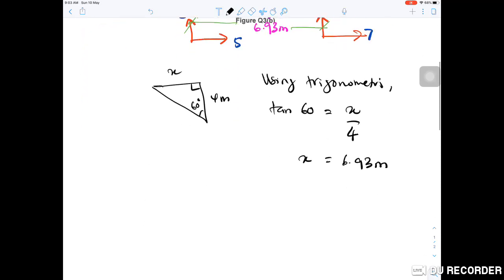Okay, now I want to start. The most important thing in analyzing truss using stiffness method, we need to divide the structure into element. Divide a structure into a series of finite discrete element. The keyword is element. Structure divide into element.